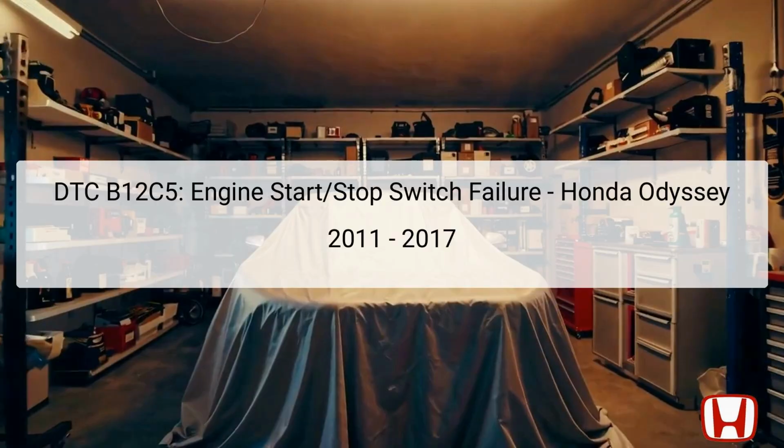The Diagnostic Trouble Code, or DTC B12C5, indicates an engine start-stop switch failure, specifically for the 2011 to 2017 Honda Odyssey. This issue may prevent the vehicle from starting or stopping the engine properly.